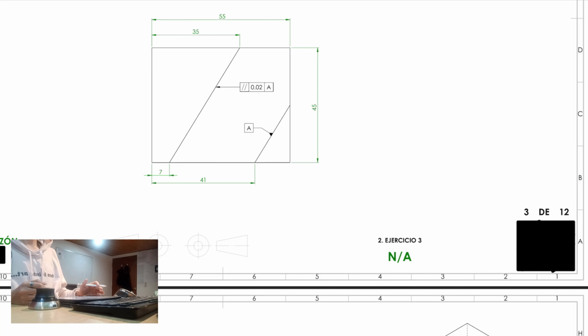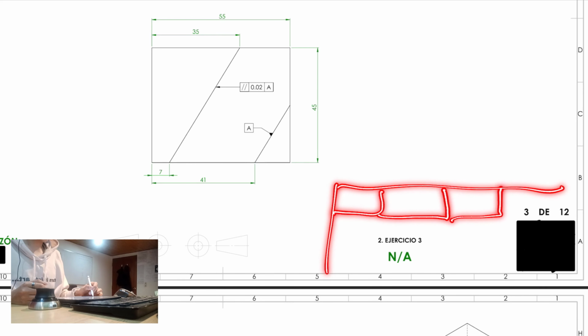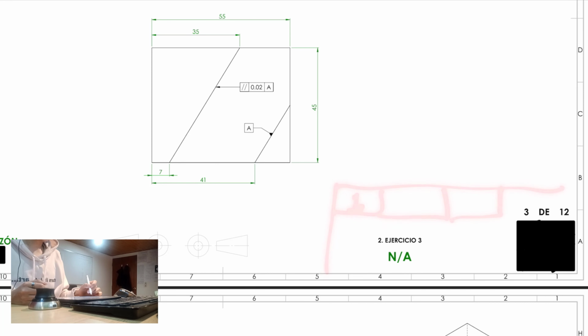Please guys, you have to be professional. You have to take into account the normativity for when you want to create an engineering draw. Within that box, you place the part name, your name, I mean, at first. The tolerances, some notes information, some manufacturer notes, whatever is necessary.